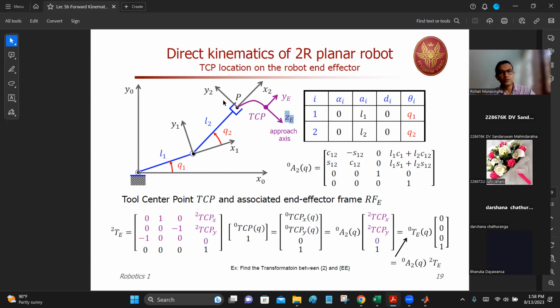So then what do you do? Can somebody suggest, take it from there and propose the second rotation? What is the second rotation? Now, your Z axis is aligned. The moment you rotate around X2 axis by 90 degrees, Z axis falls onto the screen. So that is done. But other two axes are not done yet.